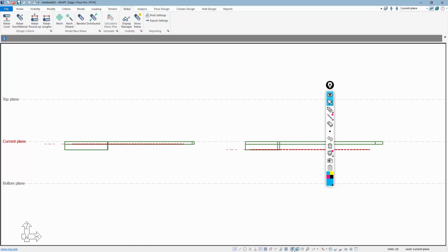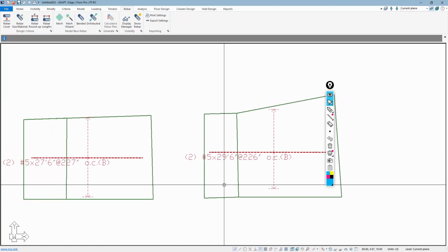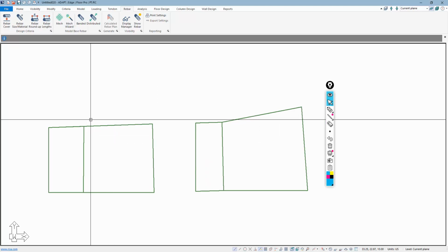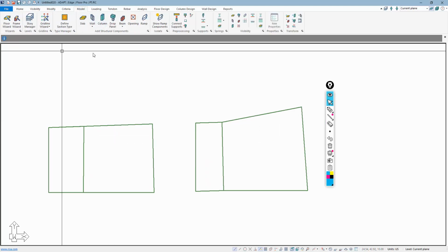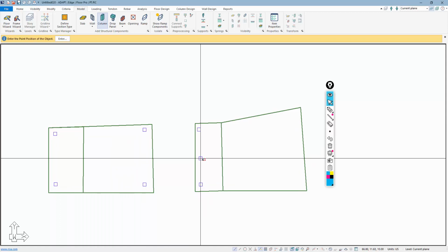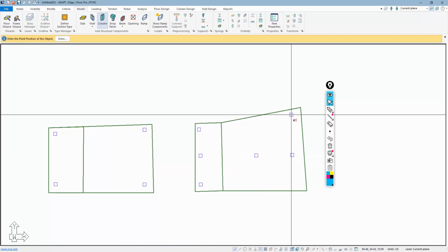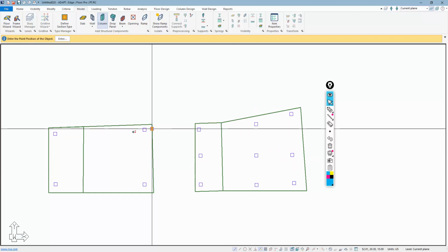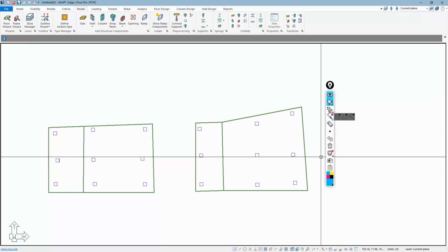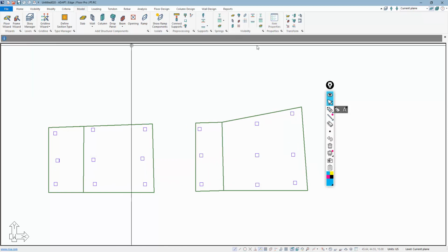This only pertains to base reinforcement. If we wanted to design this slab, and we might have columns here, and maybe a third column. Let's say we have something like this, and along this column we're going to generate design strips.